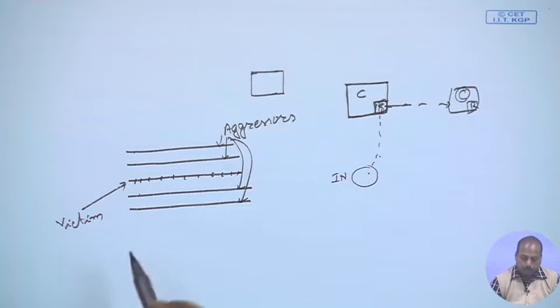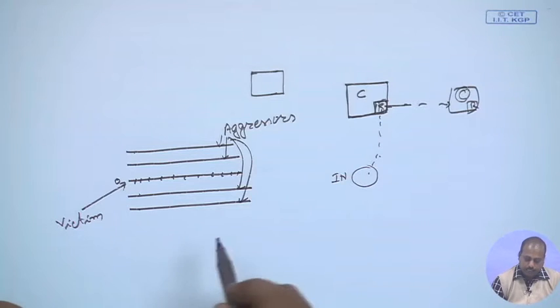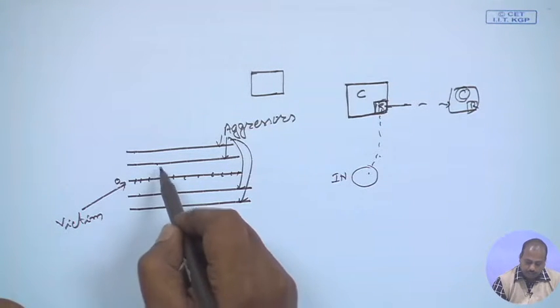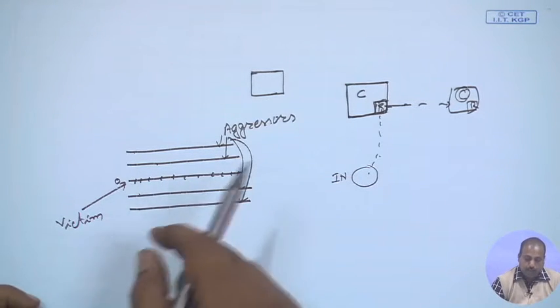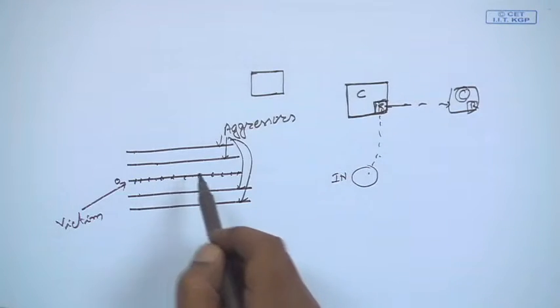So, maybe this line is at 0, but there is a transition in the aggressors. Since these links are operating at a high frequency, we have capacitive coupling between them. And if it is in the gigahertz range, then there may be inductive coupling as well. Those coupling effects will affect the logic level that you get here.